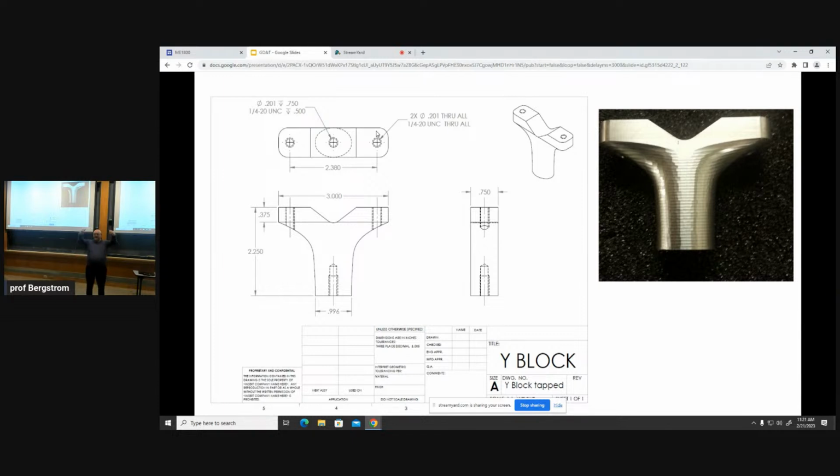I wanted somebody to say tighten the tolerances because that's the natural reaction, especially when we're young engineers, right? When we did the thing with what's the best car, a lot of people went to the Mercedes side because they tend to design cars with tighter tolerances. One theory is that the components last longer. The thing is, tighter tolerances are more expensive to make, and they're more likely to fail with a little bit of wear. So I think you have to look both ways.